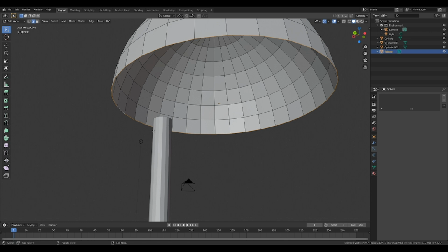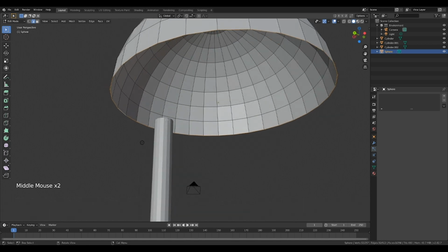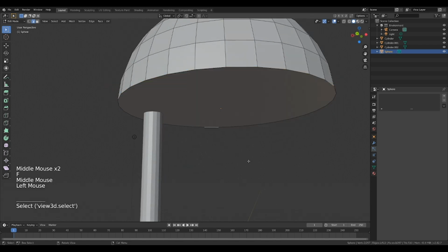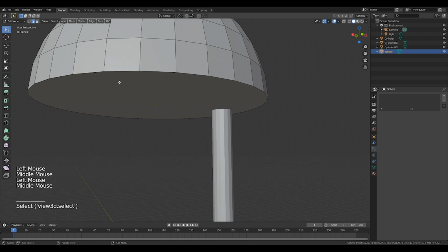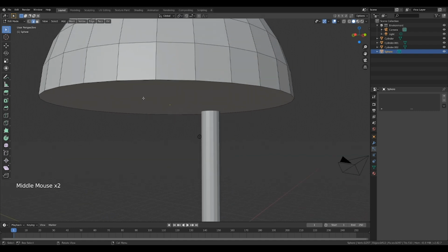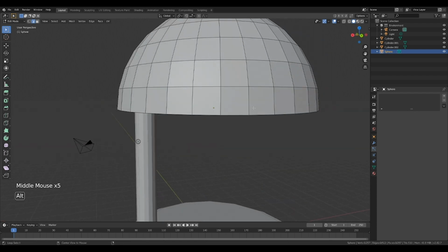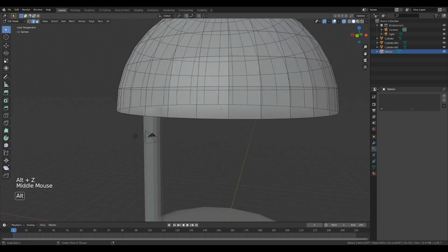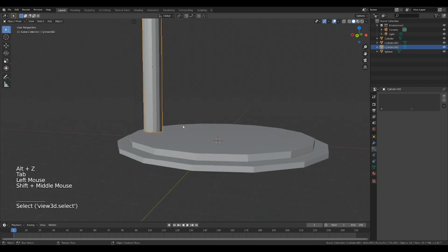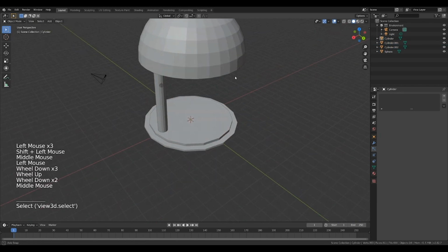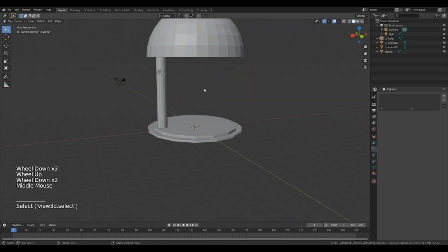And you're going to press F on your keyboard, not to pay respects, but to actually just fill. So you press F and then you have filled the bottom of your dome. Yay! Now you have the dome, the cylinder, so the column, and the 2 base cylinders. This is pretty much an old well to me.